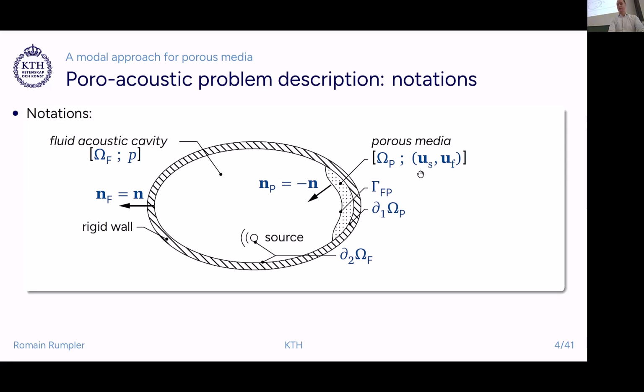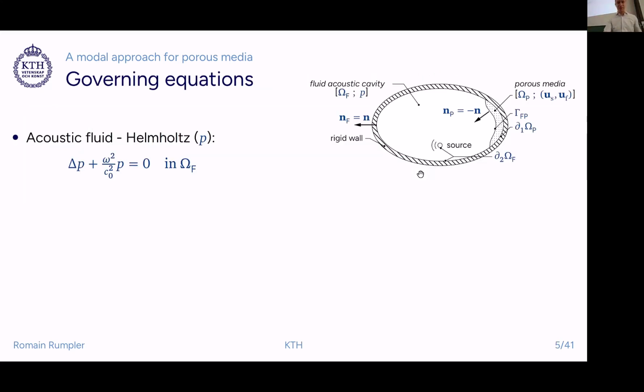And you can see here the formulation that I will use is one where instead of having the solid and total, you have the solid and the fluid phase displacement. This is the one dating back further in time than the one that was proposed by Olivier. That's the one that Biot actually introduced, that was enriched with the different parameters. And since this is very aligned with solid mechanics, I will try to see, well, can we actually come up with a modal basis that doesn't have the typical nice properties outcome if we use that for the poroelastic materials, but that we can still use in a decent way there.